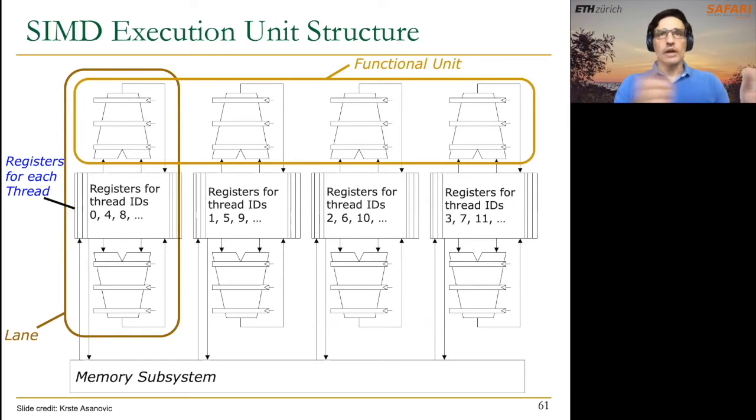And again, you have just seen a GPU core, and essentially a GPU core is the same thing that you have here. It's composed of SIMD functional units, and each of these is divided into multiple lanes, and these lanes have different execution units that can read operands from registers.